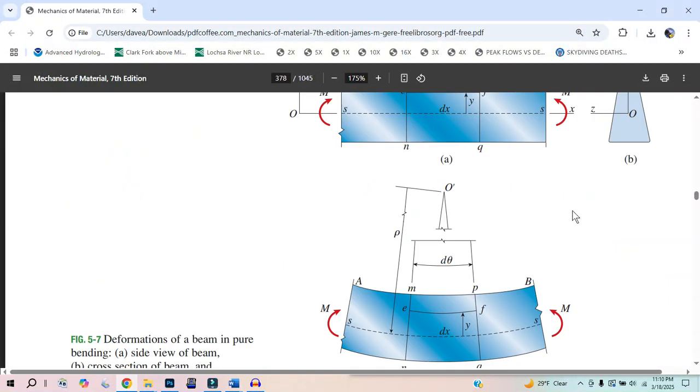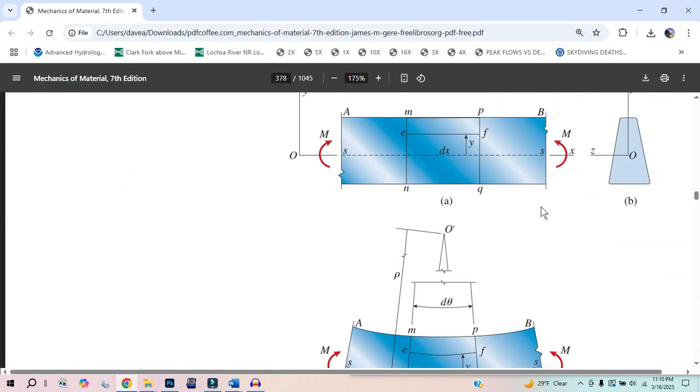So what we're saying here, and you might not be able to see this, is that if I do bend this, I guess it doesn't have to be this way, but let's just say we kind of know that the top crunches in and the bottom stretches out. Well, there must be a point somewhere. It could be directly in the middle.